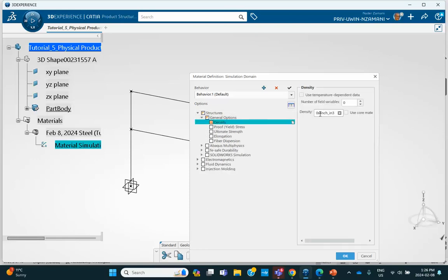Now remember, density, I already changed my unit, but I said that if you put a 0 here, it's going to come back with an error message. I'm not going to do that, so I'll just change it to whatever I said, which I believe was a dummy density of 0.001. It doesn't matter because we're going to assume that the mass of the columns are negligible. That's why we have a small density. And the top and the first, second and first floor are actually rigid entities. Okay, so that's this.